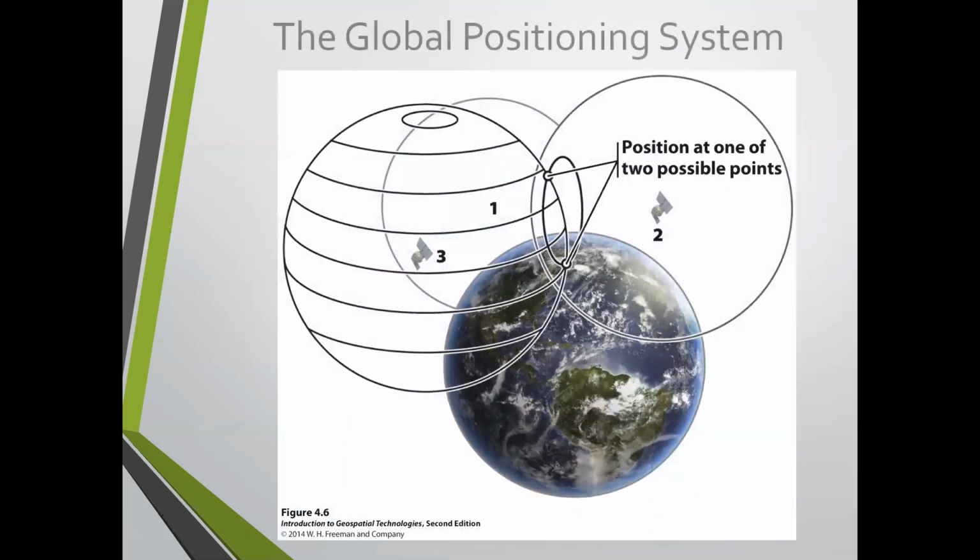There's a picture here, and this is also in your book. This shows it a little bit better. So you notice you got a receiver set up down here somewhere. This satellite's giving you information, that range, so it generates this sphere, and this satellite's giving you this, so it generates this kind of sphere right here. You notice where the two spheres intersect. You have this area here, and once we intersect that with a third one, you got two possible positions that could exist. Now, one is obviously going to be way higher, so it could be weeded out because this one would be way above the Earth, and this one would be down. The one you're talking about. But realistically, that's probably not good enough for surveying, so we would want to add more. So the more intersections that we get, the better we get.